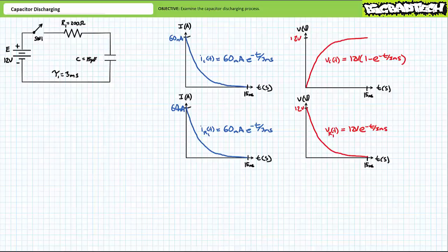I'm your instructor, Jim Pytel, and today's topic of discussion is the capacitor discharging process. Our objective is to examine the transient or time-based analysis of the capacitor discharging process. We'll learn discharging capacitors can supply a brief surge of outgoing current, where the duration and intensity of this current surge is determined by the electrical properties of the circuit under inspection. Additionally, we'll learn that during the transient discharge process, voltage across the capacitor drops.